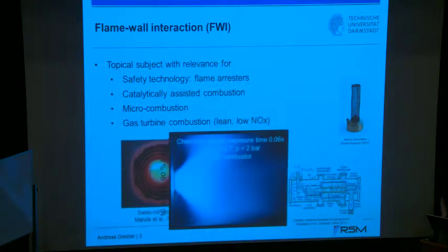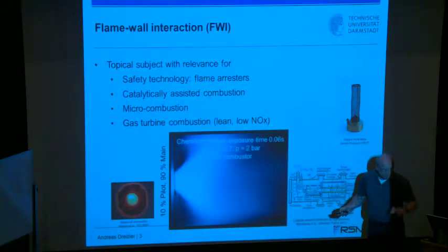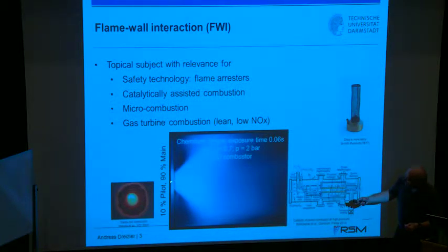Very important. Modern gas turbine combustors are operated overall lean to get low NOx levels. You see here a photograph of our combustor, where you typically, that is true as well for others, have a wide spreading angle over here, such that you have the flame with its heat release partly interacting with the wall and the effusion cooling.